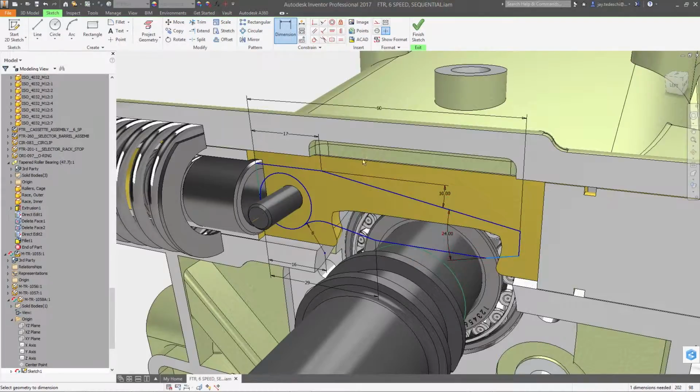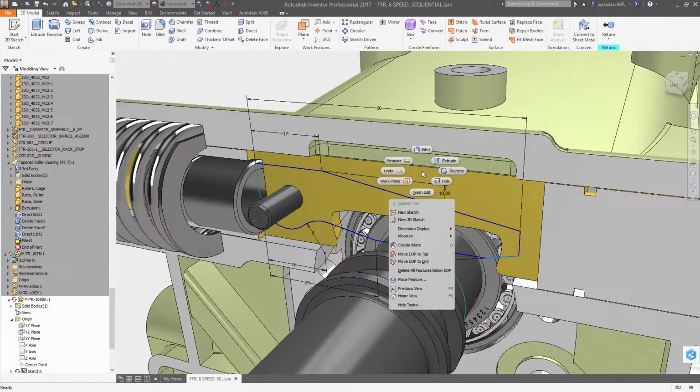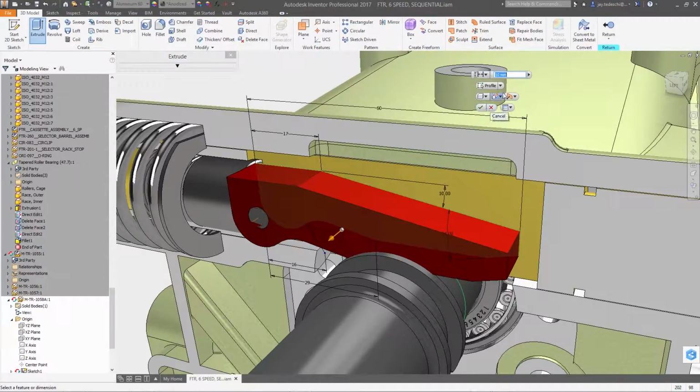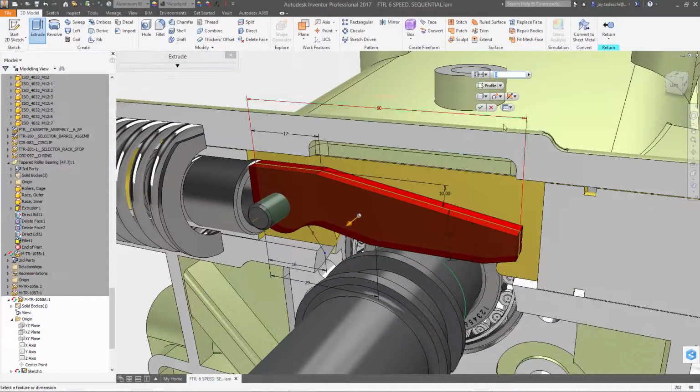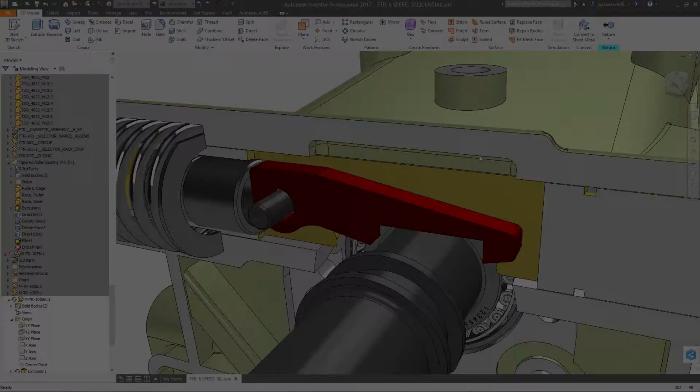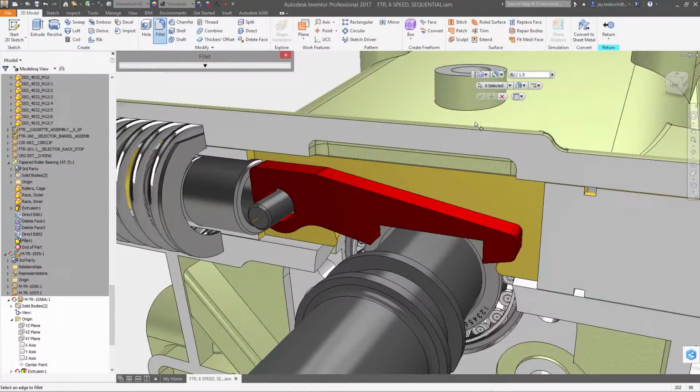3D modeling works in much the same way. Clicking on the sketch brings up different options for turning it into a solid model, and from there, you can use the handles to drag and preview the new geometry, or use the mini toolbar to key in exact dimensions or select different options for how it's built.